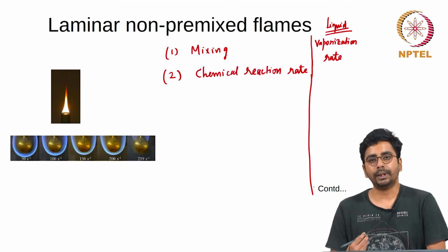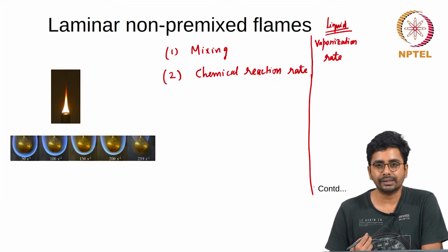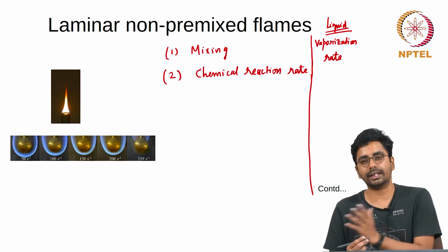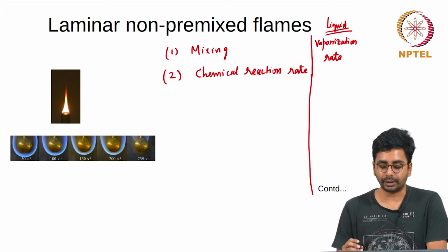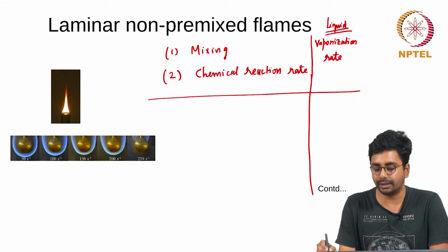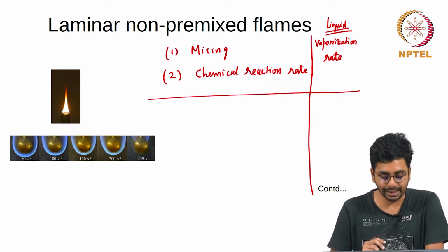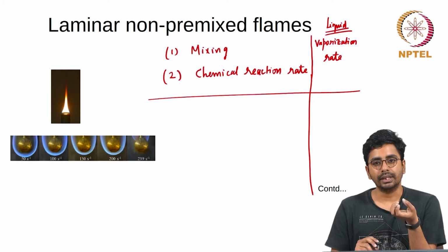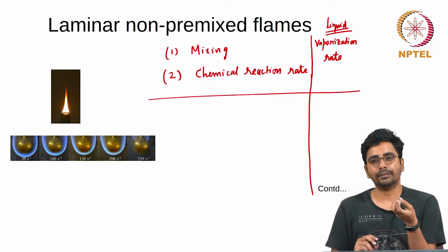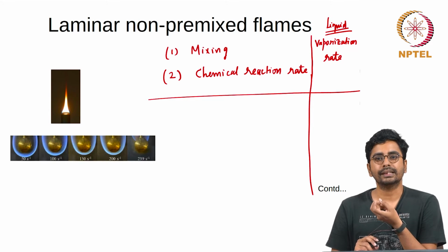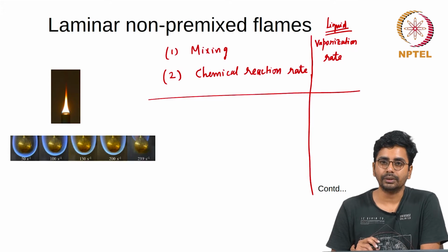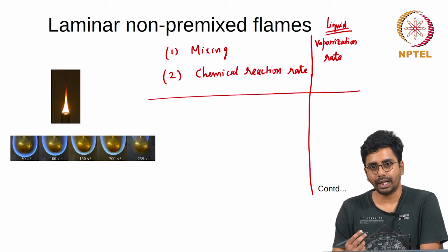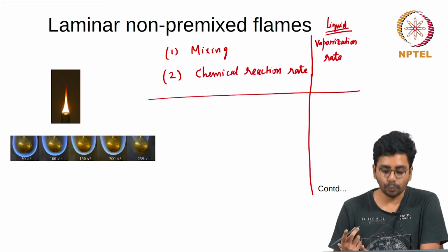Okay. But of course there are situations where this is not. I mean if we are not thinking about liquid propulsion systems, if you look at composite solid propellants, another example that we discussed in detail in the course, we saw that whether the burn rate of a particular AP particle size is controlled by chemical reaction rate or by mixing is a function of pressure and the AP particle size. Why is this?